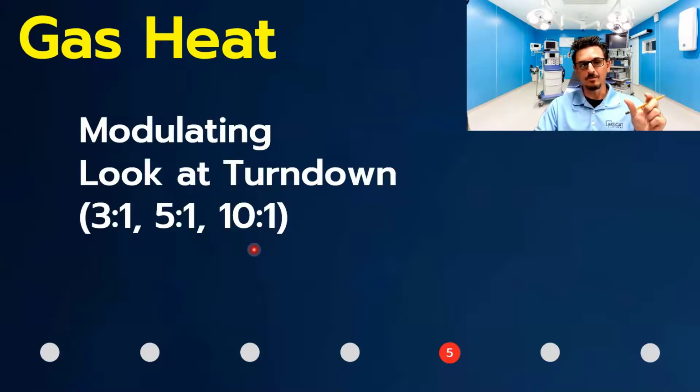If it's 5 degrees, it's probably not a problem. If it's 15 degrees, maybe you want to look at using electric heat instead. But just be aware that that is something to check. Make sure it's modulating, and always check the turn down. Some people will actually do, in the northern climates, gas heat, and then an electric heater in the duct for just the extreme, precise turn down they need as a supplement on those days where they need it.